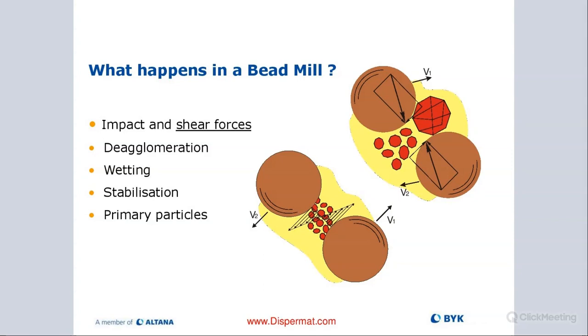They move all over the place. They impact the sidewall of our media mills, the rotor. They wear everything down over time. So the choice of proper rotor material, or maybe even a ceramic-lined milling chamber to reduce the wear of the equipment, becomes very critical because there's really a lot going on inside of our mill.